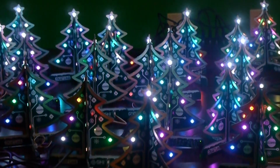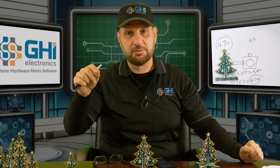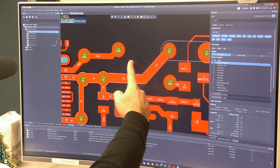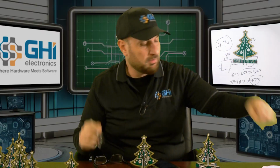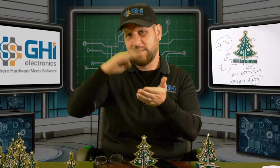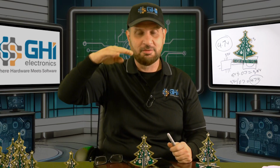Now I still have over 100 trees that I need to ship in like 2 days, and I cannot just redo them. We cannot trash them. So we need to find a way to fix these trees. I went back to the design software and checked the traces, and sure enough, I found a trace between USB, because USB is the 5-volt source, going into the tree. And that's on the surface. This is a 4-layer circuit, so if it was on an inner layer, it would be very hard to get to. It was right on the top.